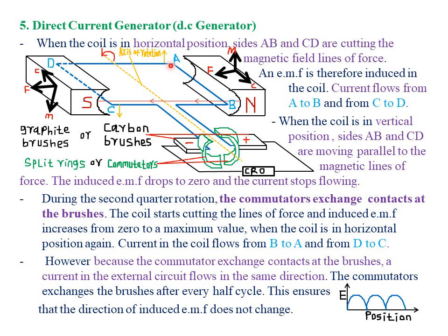So when the side AB is moving upward, place your thumb pointing upward. Then of course the magnetic field always moves from the north pole towards the south pole, so you point your first finger from the right-hand direction towards the left-hand direction. Then observe the direction of your second finger. You realize that your second finger is pointing out of the paper, along the direction of AB. That predicts that the induced current or EMF will be moving from point A towards point B.